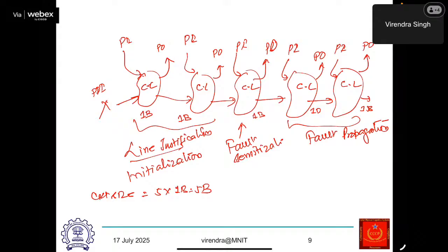Assume that one circuit has 100 primary inputs and say 50 primary outputs. Now my total unrolled circuit will have primary inputs, that is 5 into 100, so that means 500 primary inputs, whose values you need to find out, and those will act as primary inputs.